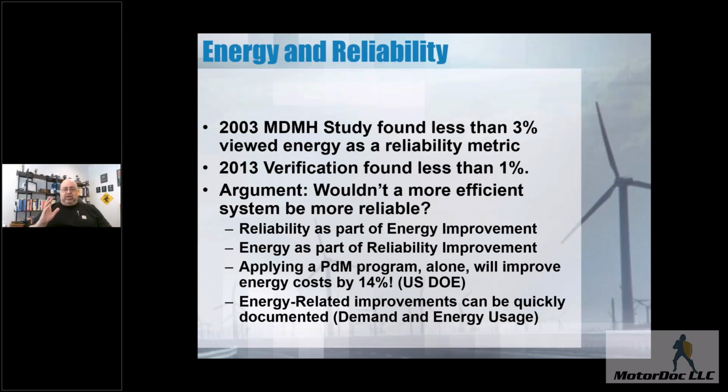You could literally have a kilowatt meter, or even more so when I show you some of the software after we do this presentation. They've got two. One's called MEASUR, without an E, and the other one's called Verify. Those are both U.S. Department of Energy software, free to download, and Verify will keep track of the energy consumption in your facility and can be tied directly into that, as well as taking care of pulling in some measurements that are sometimes challenging to get.